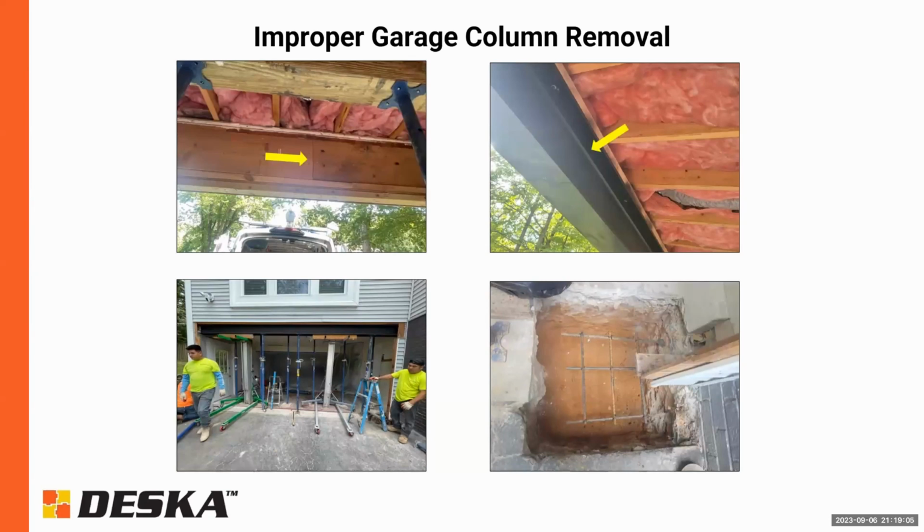In this case, it was a 10-inch, I believe it was W10 by 39 steel beam. So a 10-inch tall beam by about 39 pounds per linear foot. So a very heavy steel beam. And you can see there it is installed. And then in the bottom right corner, the footings at each of the ends needed to be reinforced as well to support those increased loads.